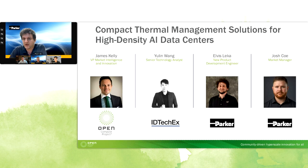And then the PG25 in the rack: the PG25, the water itself, will be taking the heat generated from the chip and taking it outside. So the water itself will be the transfer media for that heat from the chip to outside of the building. That's the main feature of the PG25 and why it's in the rack itself.